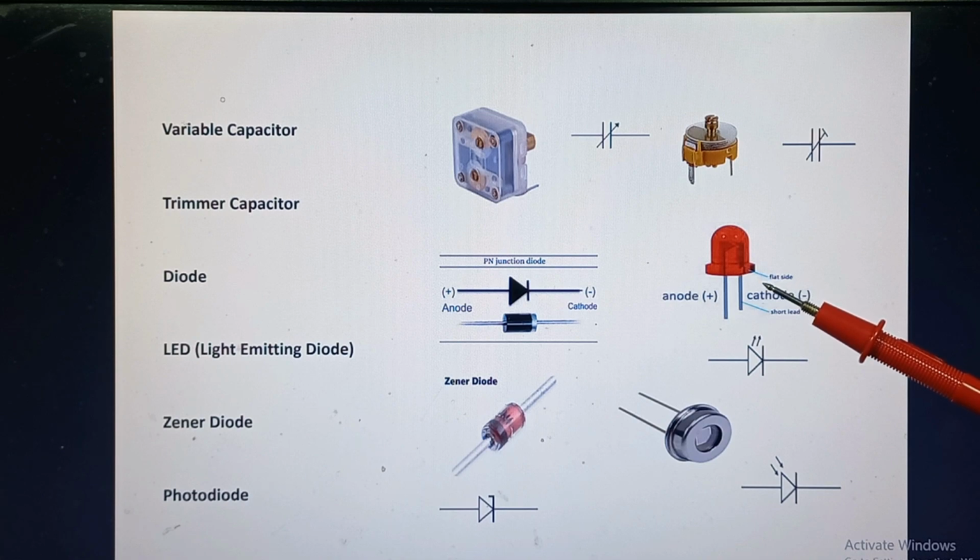LEDs are available in red, orange, amber, yellow, green, blue and white. Blue and white LEDs are much more expensive than the other colors. The color of an LED is determined by the semiconductor material, not by the coloring of the package, the plastic body which is called the package. LEDs of all colors are available in uncolored packages, which may be diffused, milky or clear, often described as water clear.